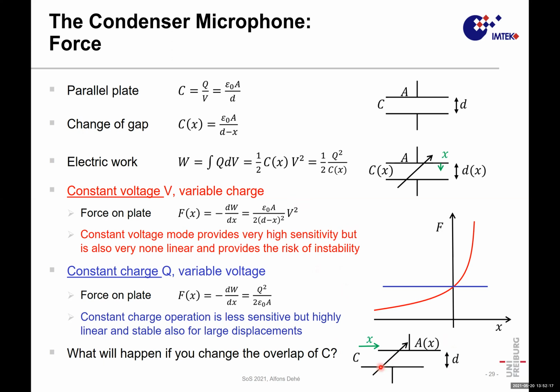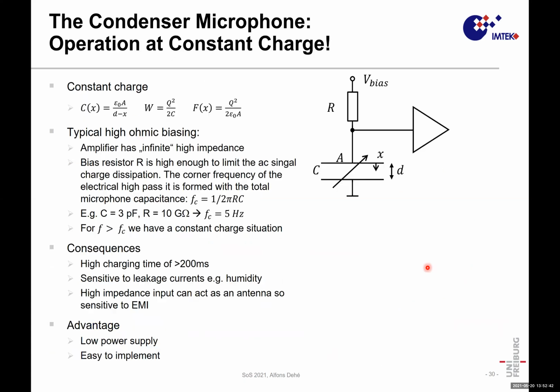Basically, then you have capacitance proportional to the area, and the area is inverse to the distance. Basically, the situation will change. You would have then to apply constant voltage to your device to generate constant force with modulation. Okay, back to the constant charge parallel plate distance changing devices.